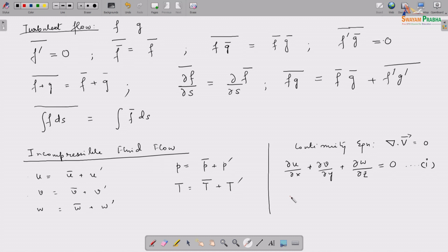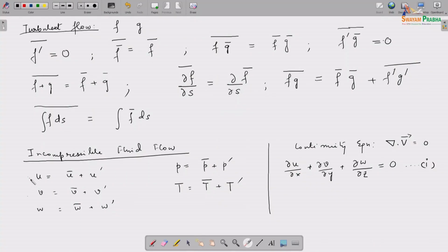Now we are boiling down to the point where we can calculate a mean value of the velocity that the flow maintains, and then randomly oscillates or fluctuates across this mean, which is defined by these primes. So, mathematically it boils down to writing out the components of velocity, u, v, and w, as sums of means and a prime. That's exactly what I'm going to do right now, and then see where this takes us.